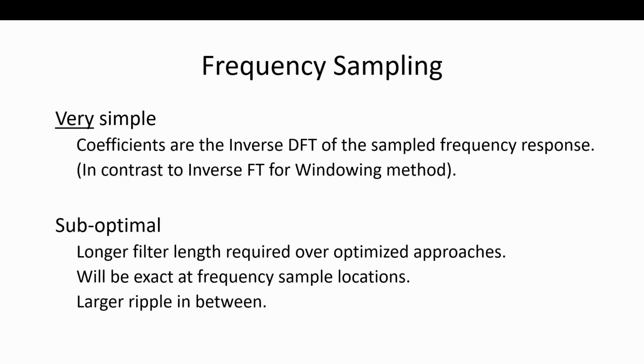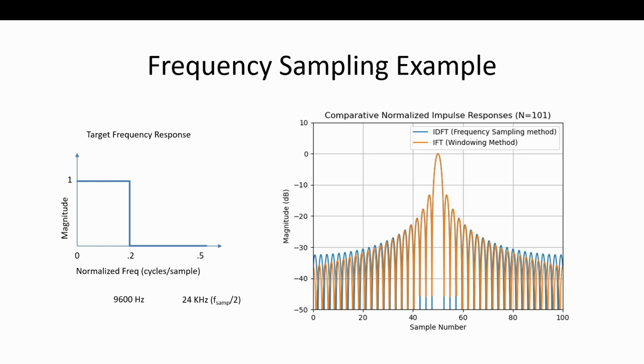With this one, we're going to say, hey, here's the frequency response we want. We're going to sample that and put that into our FFT, saying these are the FFT samples. Inverse FFT of that, that's frequency sampling. Do you see the difference? You see the difference?